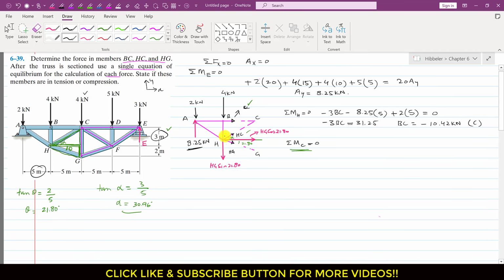Now if I apply the summation of moment about point C equals to 0, as we can see this cos component is producing the counterclockwise moment about this point C, so I will write plus Hg cos of 21.80, and the perpendicular distance of this cos component from point C is this length, which is 3 meters, so I multiply this with 3.